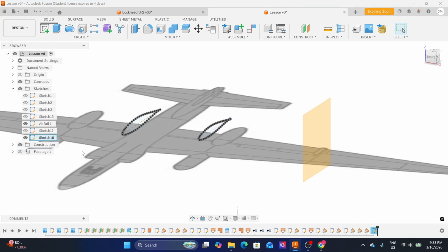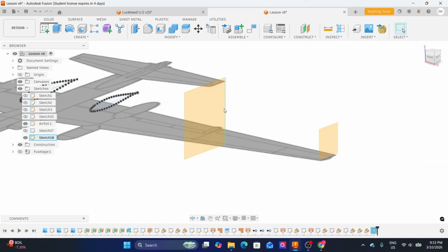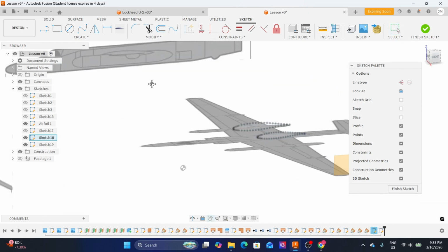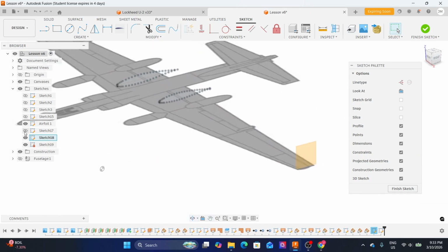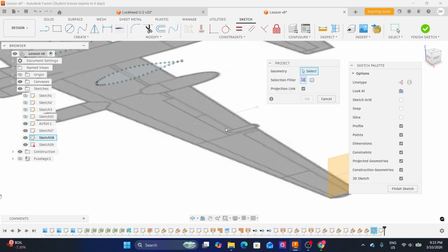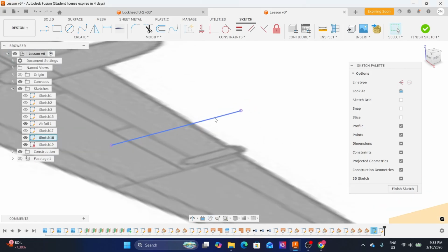Oops, sorry. So construction, and then next would be here. I'll select this plane and create a sketch. Let me unhide sketch 17 so that I can project this line. Press P on my keyboard, select this line, press OK. Let me hide sketch 17 again, I don't need it yet. Then directly convert this into a construction line, so select it, line type would be construction.